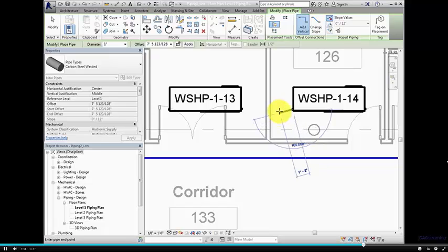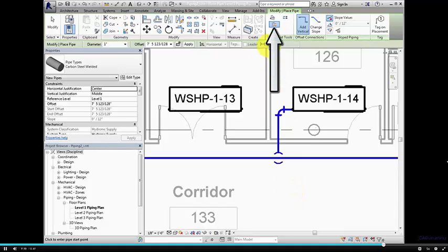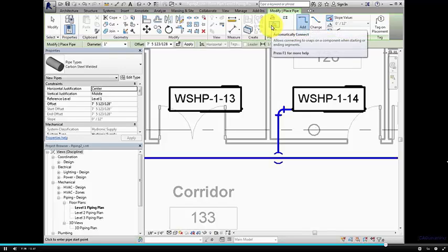Now you are creating a pipe segment for that connector. Create a horizontal segment and then click the main pipe to place a vertical segment. When you do, Revit connects the vertical segment to the main pipe segment by placing the appropriate fittings, and it places another pipe segment perpendicular to the work plane. This is because Automatically Connect is selected in the Placement Tools panel of the contextual ribbon. The pipe tool is still active, so click Modify to end the command.